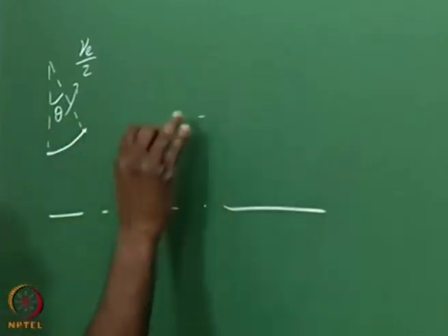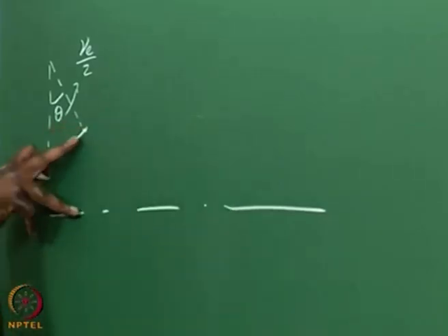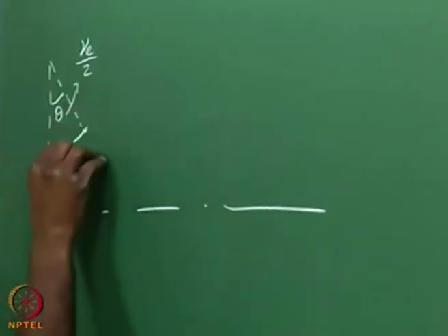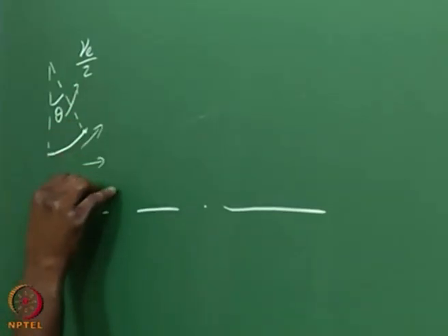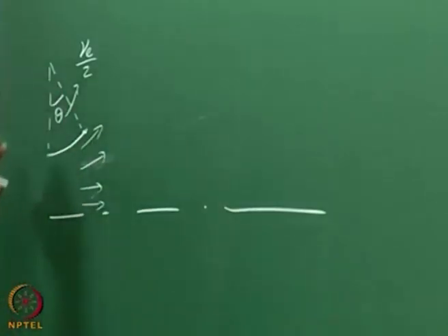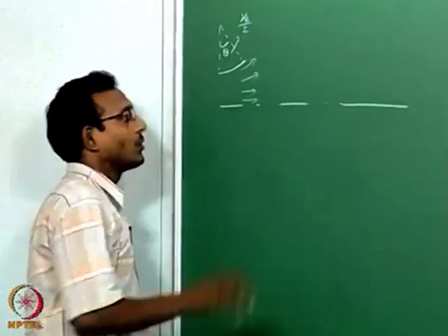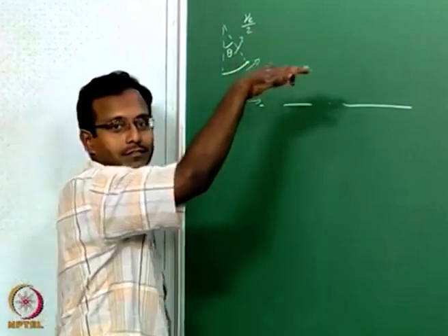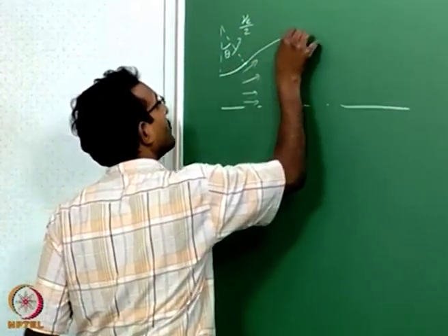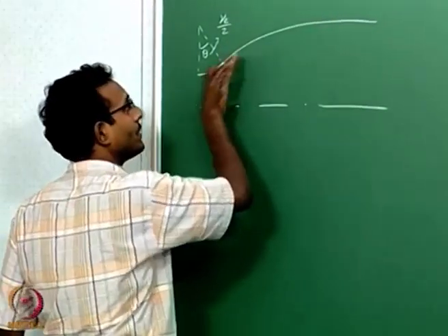points on the wall such that these points, if you notice what is happening in this region, it is expanding, the flow is expanding. Now if I keep going this way, I will get velocity vectors like this. As it goes up, velocity vectors are out, right, but we wanted parallel flow at the exit. So now we have to turn those streamlines back. That is the other reason why the remaining lines will be turning back. The remaining wall points are designed such that they will be turning back.